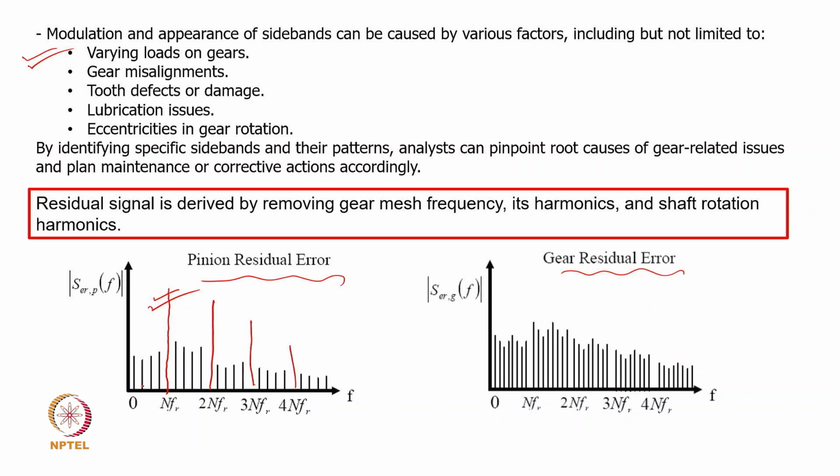But if there is a good tooth, then I may get a response only in this manner, or maybe a very small signal, which may be a kind of noise. While if the gear tooth is damaged, I'll get a little more sideband, so I can analyze it.